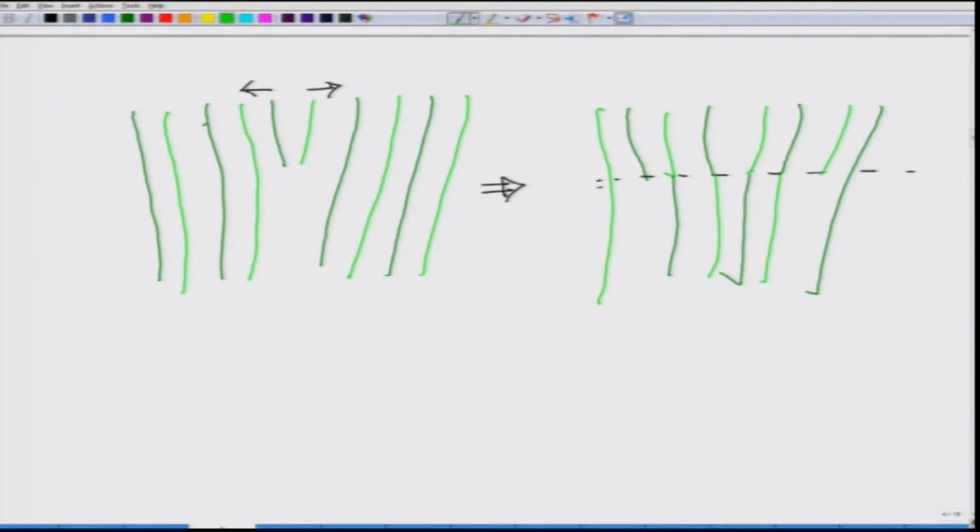Okay, so here this was your extra half plane, which is dark green colored, this is extra half plane light green colored. So, this is a perfect crystal, but now these two want to move apart. So, extra green plane comes over here, the lighter green plane comes over here, but the bottom side of it were still in the same place, because only the top parts are moving, and because of that what you will get is called the stacking fault.